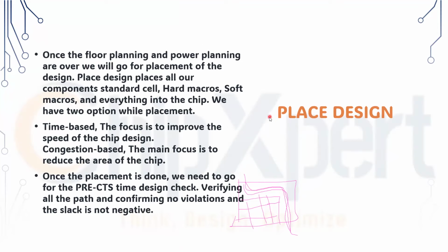Once that is done, we'll be placing all the standard cells or gates in a design, in a layout way. It will connect all the connections that are required for the power, and it will ensure that each and every standard cell is placed without any issue. So this is how the placement of standard cells will happen. Once that is done, we will start verifying the timing analysis for setup. Then we are good for the placement.